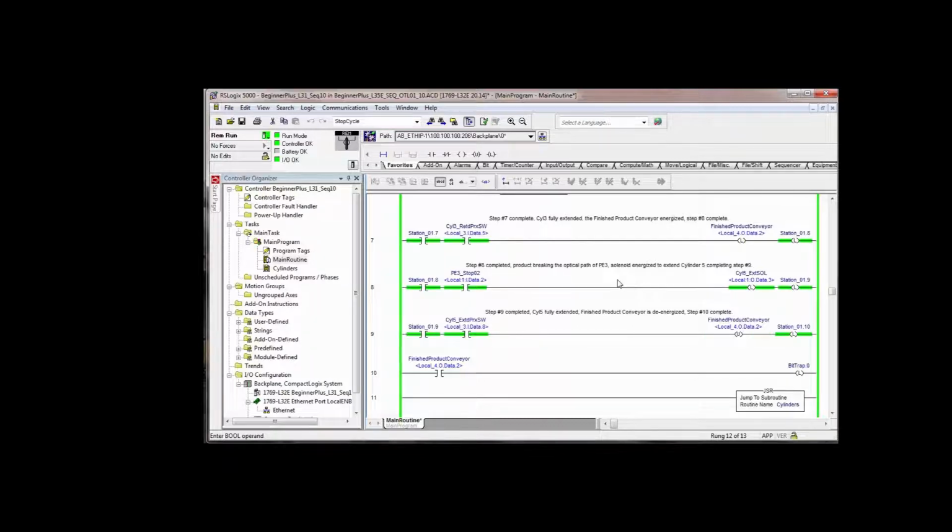If the communications happens to look at that bit at the right instant, in other words, between this rung and this rung, there's microseconds between executing this rung and this rung. So if the graphics happens to update when this rung has just been executed, it's going to show these bits as on. However, if they actually were on and staying on for any length of time that would affect anything, then this rung right here would latch that bit. And there is no instruction anywhere that's conflicting this bit, in other words, unlatching it, turning it off.